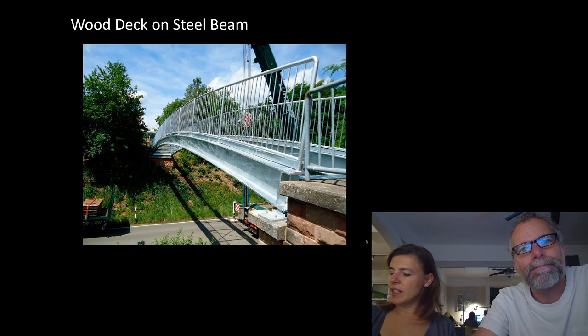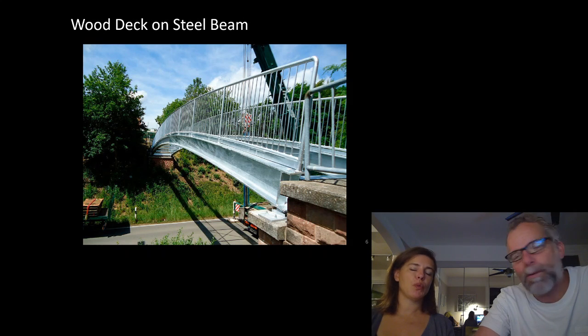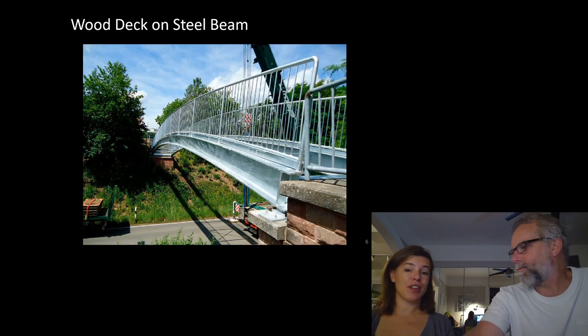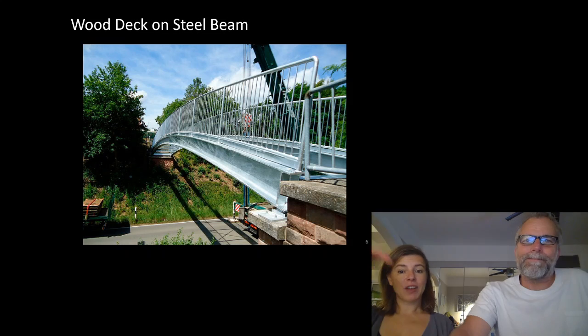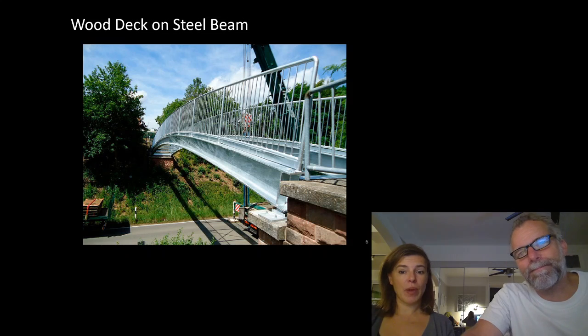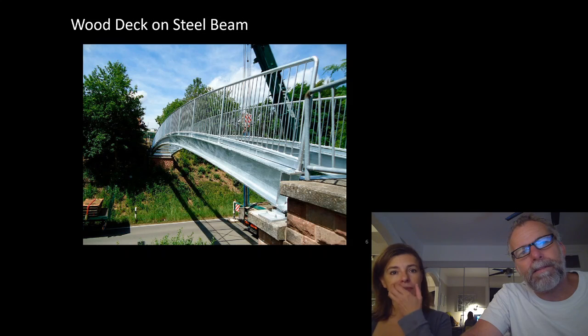I just always think of it as not an arch on its own. It's always an arch, and it's always a truss. It's just a truss where the bottom chord is flat, the top chord is the arch, and there's cables that are like the web. So this is a nice place to start.